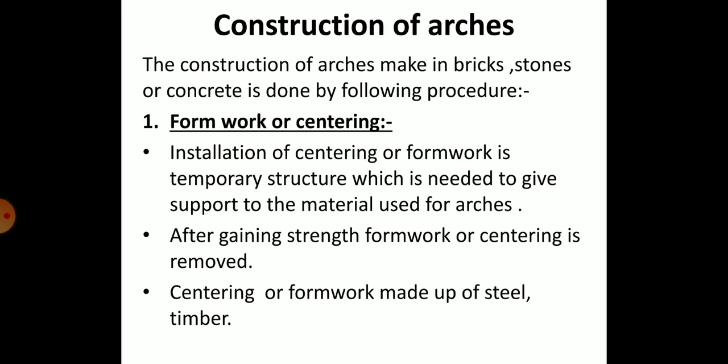So the construction of the arch, there is a formwork or centering. So what is the construction of the arch? There is also one corbel arch. So how to construct the arches? In the procedure of the construction of the arches, there are three steps: the formwork or centering, the laying of the stone blocks or bricks for arches, and the removal of the formwork or centering. So the first is the formwork or centering.